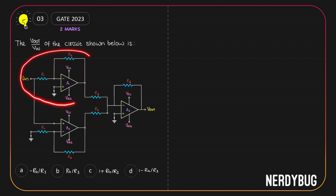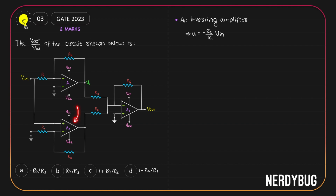So this much is basically just an inverting amplifier. Let us take its output and call it V1. Since A1 is an inverting amplifier, we can write the output V1 is equal to minus R2 by R1 multiplied by input. Let's take a look at A2 now. Its input is given at the non-inverting terminal. We have R1 and R2 over here. So A2 is basically a non-inverting amplifier. Let us call its output V2. Since A2 is a non-inverting amplifier, V2 will be 1 plus R2 by R1 multiplied by the input.